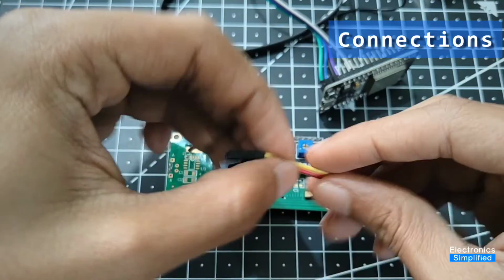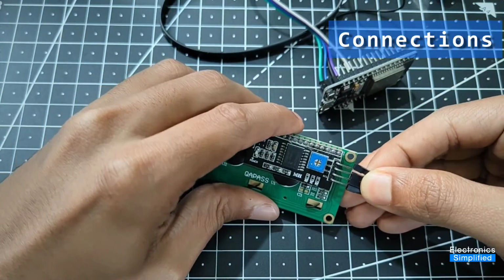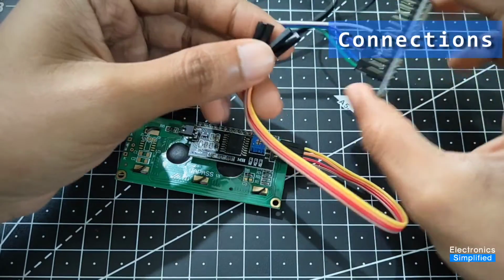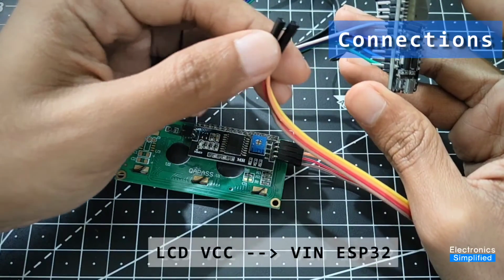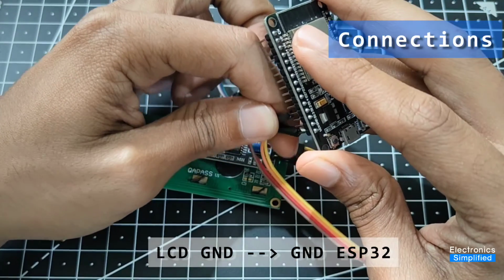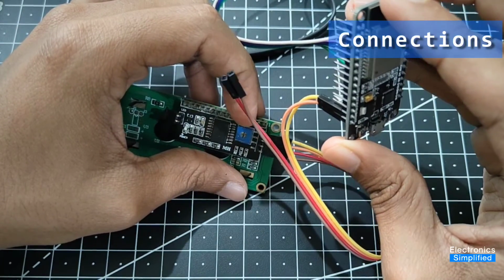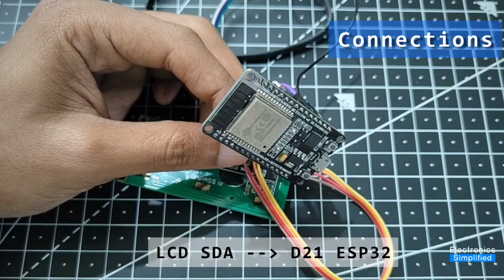LCD. So again the same process, the ground and the VCC will go to ground and Vin. So ground and Vin, I'm going to connect them simultaneously. Yellow is ground, orange is VCC, red is serial data, which is connected to pin number 21.